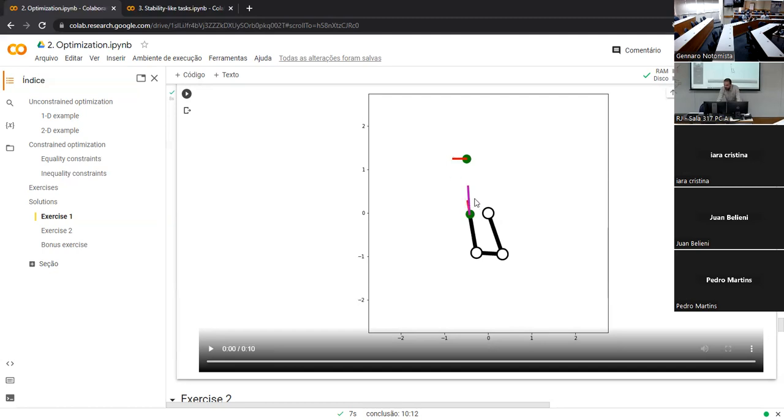So in this case, you see we have the forward kinematics represented by this green dot and red arrow of the end. And then we also have what we saw in the differential kinematics. So this magenta line here is the velocity again, right? Resulting from the q dot. So if we run this program, we have something like that that achieves these.